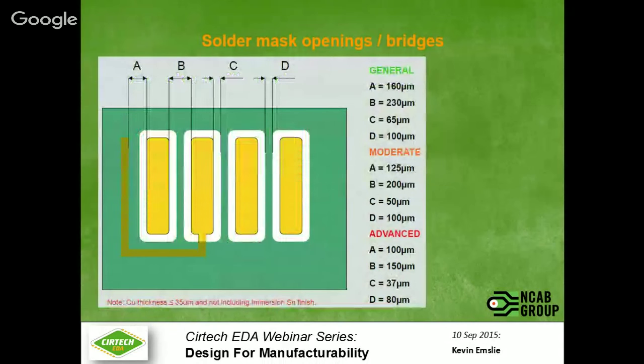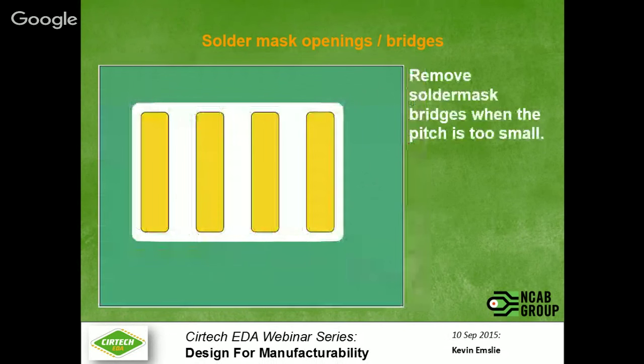Okay, maintain the specifications or the capabilities of the manufacturer. So be aware of them, especially when it comes to solder mask bridges. And if you have a component that has a pitch that cannot accommodate a solder mask bridge, it's better to remove the bridge completely.